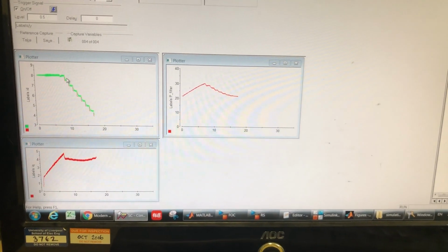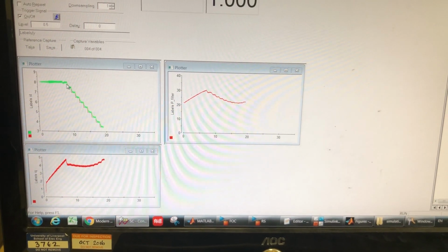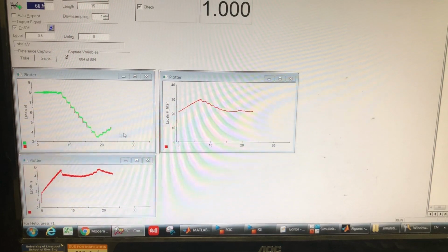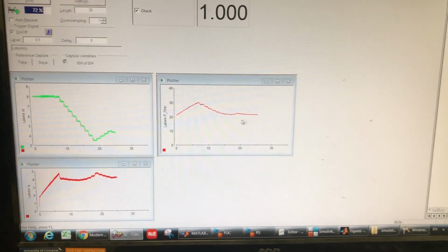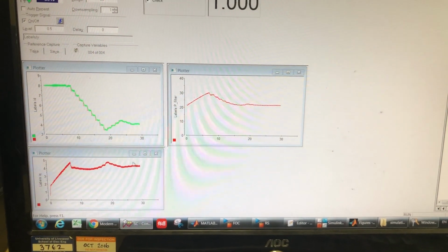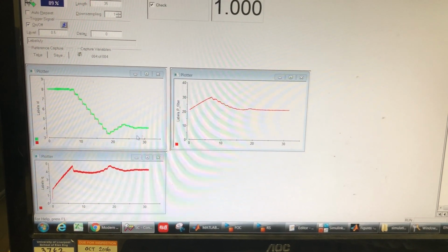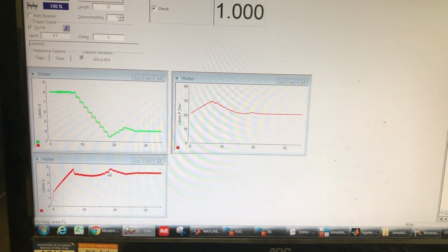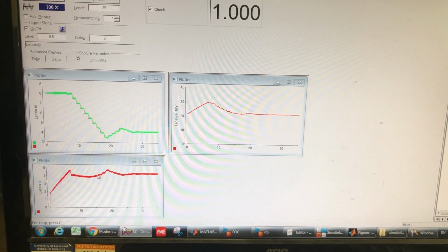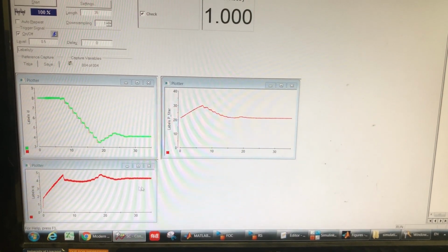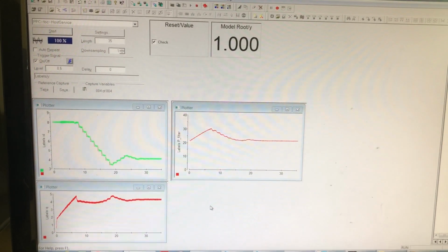As you can see, after the transient stage, the current will be reduced to find the optimal working condition. On the other hand, the input power is also reduced. When it becomes a little bit stable, as you can see, the torque current level is also a little bit increased to maintain the torque unchanged.